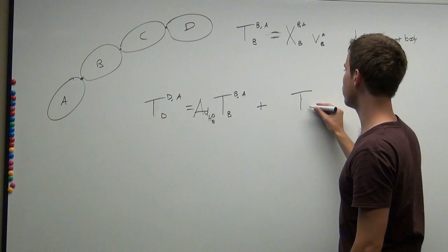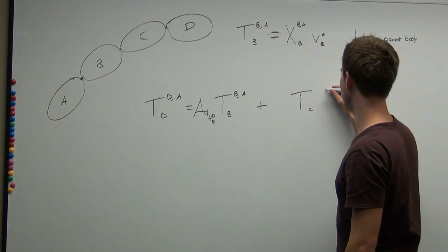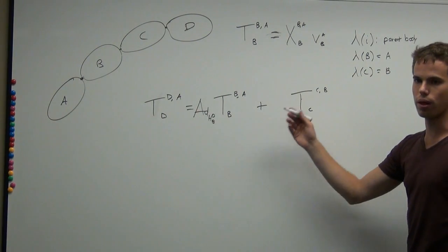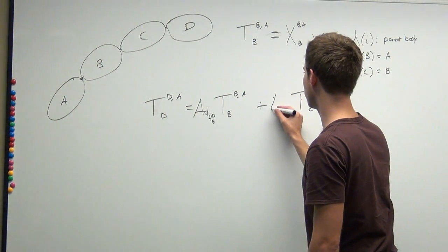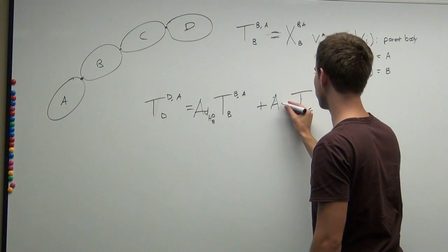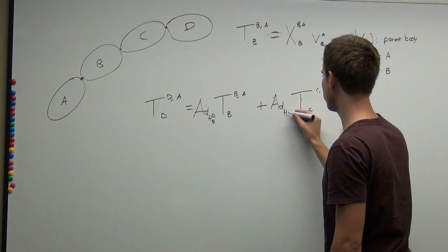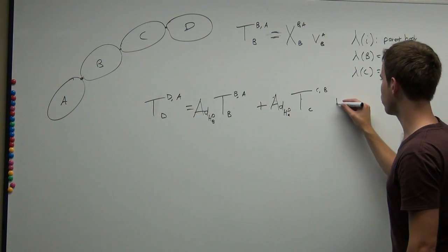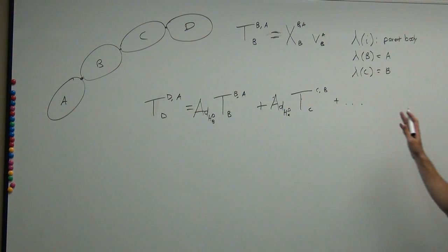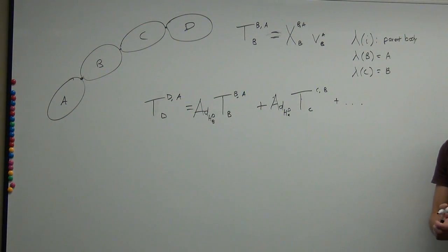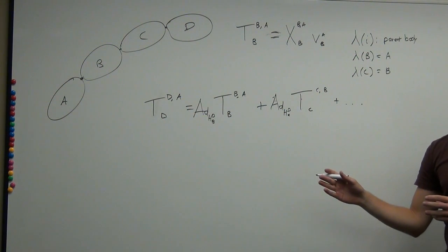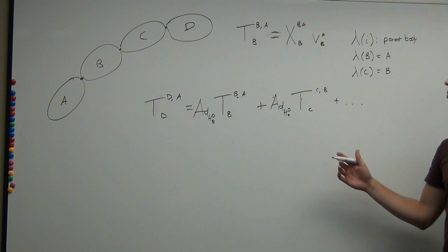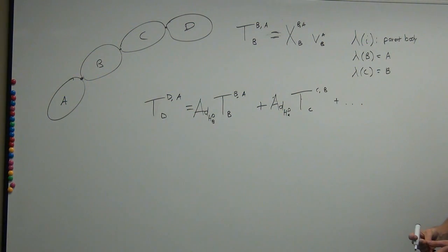So we know T of C with respect to B, expressed in frame C. And we just do the same trick of transforming it to that frame D that we want everything to be in, H D C. And so you can see the idea of how this works. You just take the local joint twist that you know in body frame and change frame it to a common frame, for example, frame D in this case.